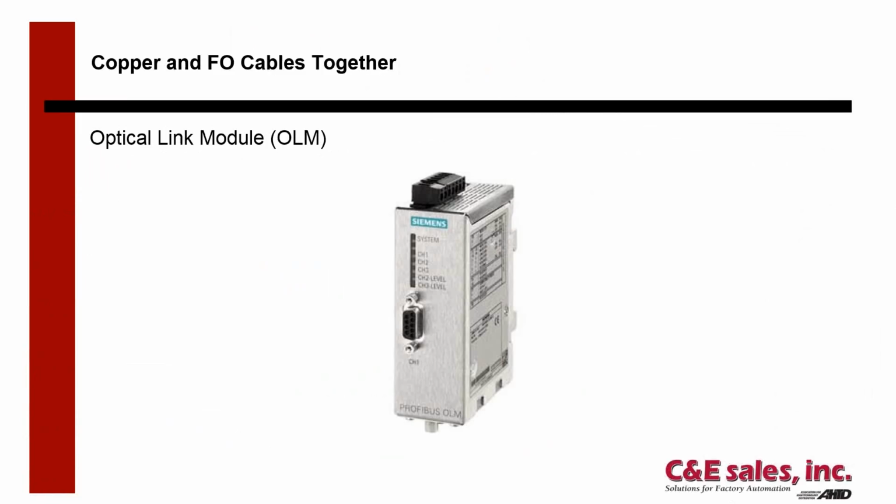Why would you want to mix your copper and your fiber optics together? What we're going to find out in a few slides is that when you're dealing with copper, the baud rate you can set is limited by the distance that you run your copper cable. A lot of times your PLC may be in a nice air-conditioned control room or a PCR, and the remote I/O and the devices you want to talk to may be in the basement of your facility. Instead of making one really long copper Profibus network and having to slow the baud rate down, a lot of people set up an optical link module and run fiber optics from the PCR down to the basement, then convert that to copper and network that out to all the devices. That saves you a lot of distance on your copper cables and allows you to run at a higher baud rate.